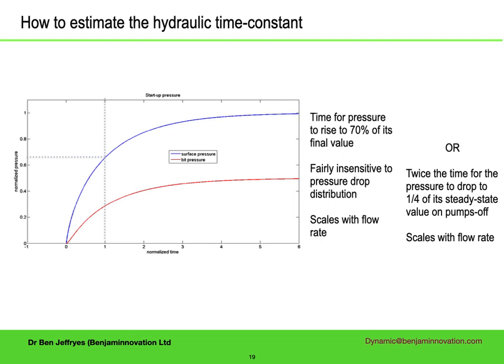As we have seen, it can take several hydraulic time constants for the downhole flow rate to stabilize. For a system with a time constant of 15 seconds, this is less than a minute, but in long wells with big pipe and oil-based mud, the time constant can be over a minute, so the stabilization time is several minutes. Acoustic measurement while drilling systems require stable flow to reliably initiate communication, so this can be a considerable problem.